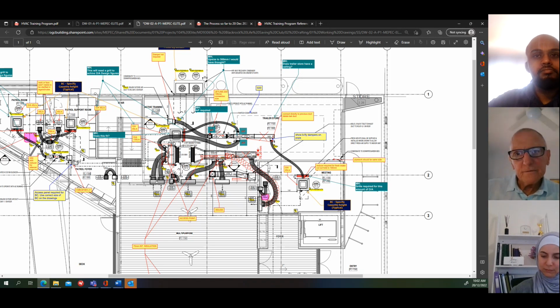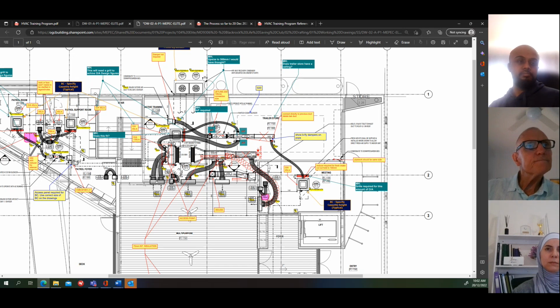It's a site function. But there may be times when someone on site, like a commissioning guy or a service person, calls you and says, oh, this drain's leaking. What's the problem? The problem probably is there's not enough slope or it's blocked up with something. That's usually the two problems. Probably more likely to be blocked up, but if there's not enough slope, eventually it's going to overflow and leak on the ceilings, and then it's a big mess to clean up and maybe even replace parts of the ceiling. So that's important to get right.